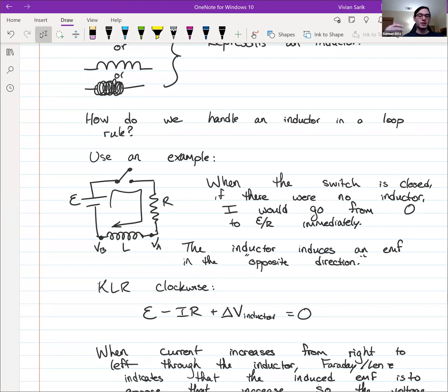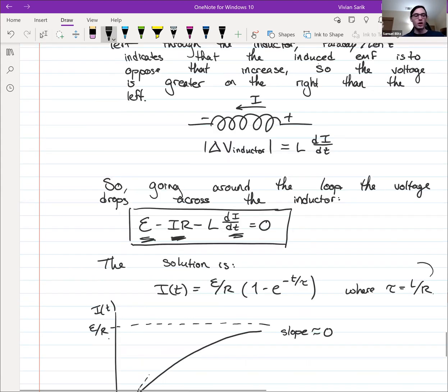In that case, the inductor will act to try to keep the current up. It will try to prevent the current from going to zero. And so it will use up its magnetic field to try to produce a current that keeps flowing in the same direction. And it will eventually decay away, just like a discharging capacitor. The current obeys an exponentially decaying formula, just like a capacitor. It has the same time constant as we found here. Tau is L over R, and so on.